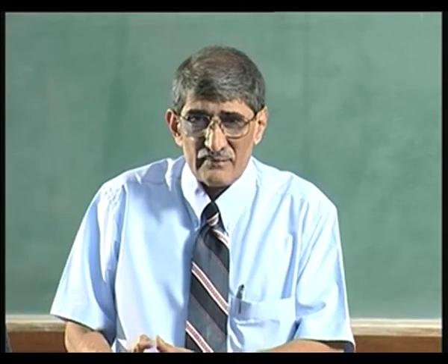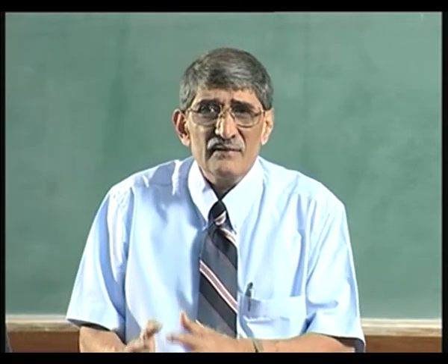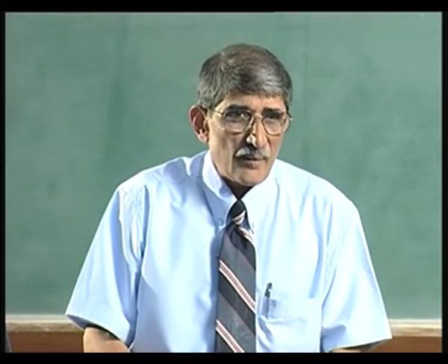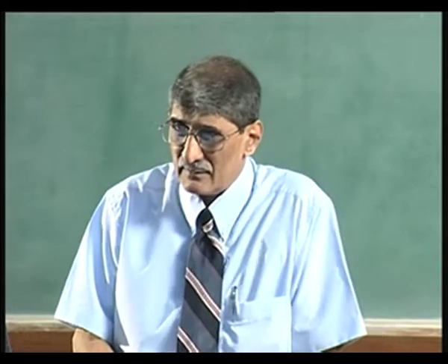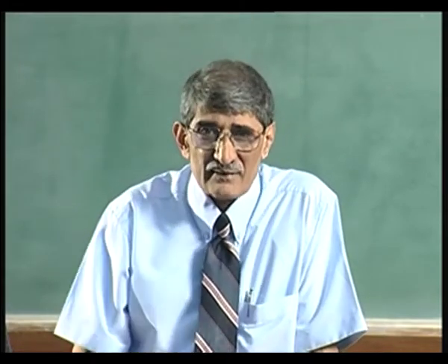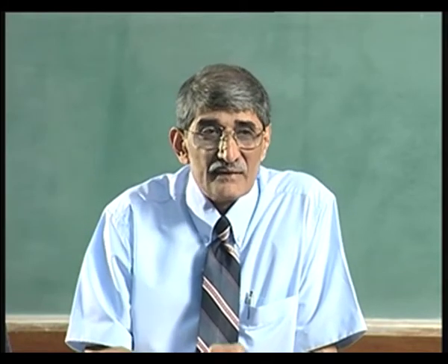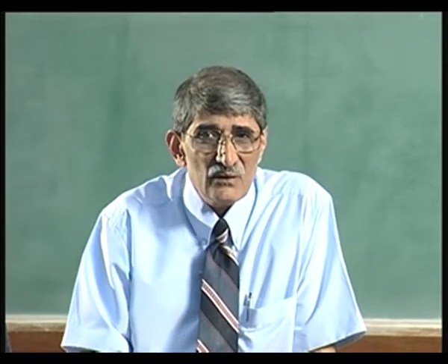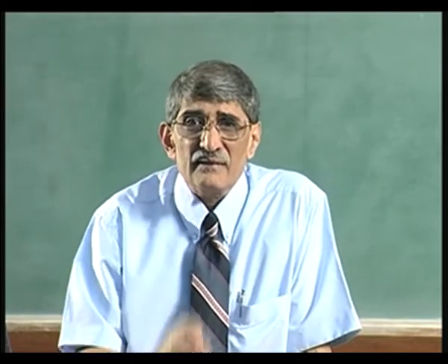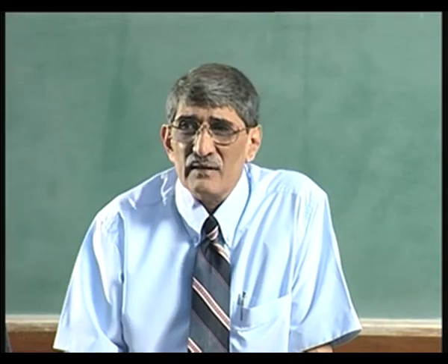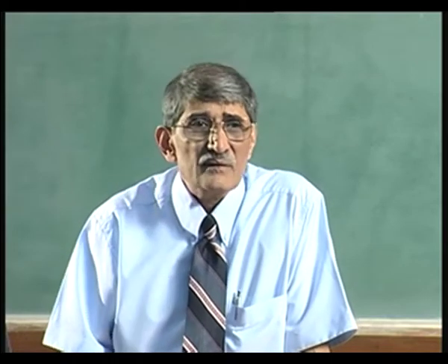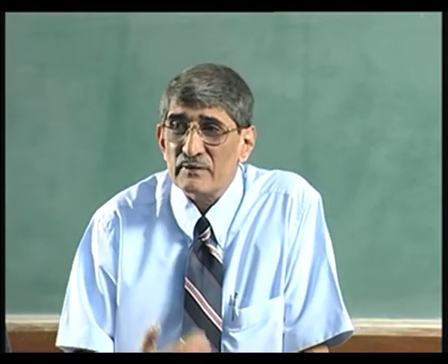I will come back to that. Right now, let us leave that, because that is one area which we have been working. MIS is the counterpart of MOS. If you are putting metal insulator semiconductor, instead of metal oxide semiconductor, deposit some insulator. I will come back to that, particularly with gallium arsenide based devices, MIS field effect transistor with silicon nitride. In fact, that work has been done in IIT Madras in great detail, the PhD by one of my students on MIS field effect transistors using gallium arsenide.